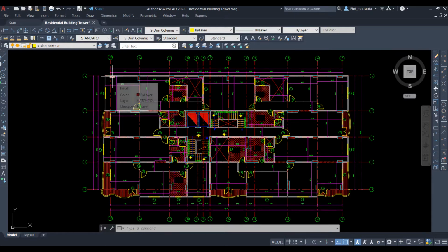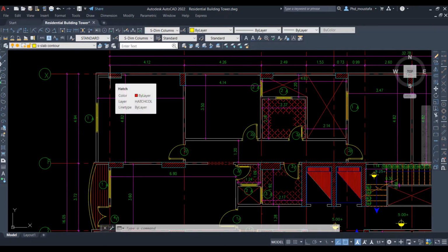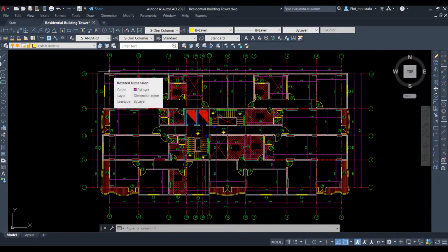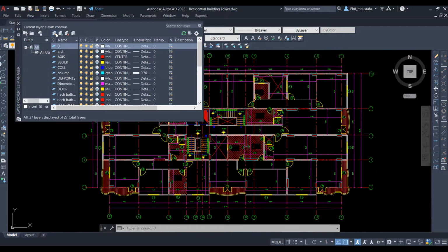The first step is to start with the layout of the slab. We need to define a layer. As you know, we are working in ETABS, so we define a slab layer. Let's define layer number one here.